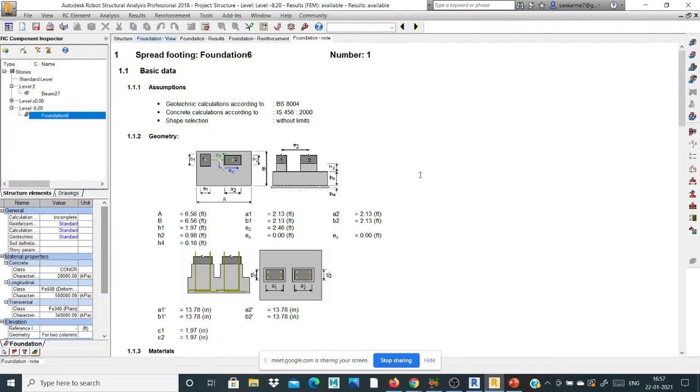Now understand how to create the frame structure in Revit and analyze it in Robot Structure, and how to check whether the values are correct or wrong in this manner, right? You check the code books also, refer to the books and others. Once you check, you know whether the value is correct or wrong, right? You calculate in an Excel sheet and spreadsheet also, etc. Right? This is just an introduction about Robot Structure and how to analyze it. You refer to the books and other code books to check whether your value is correct or wrong.